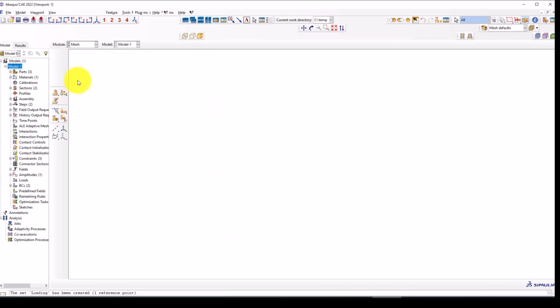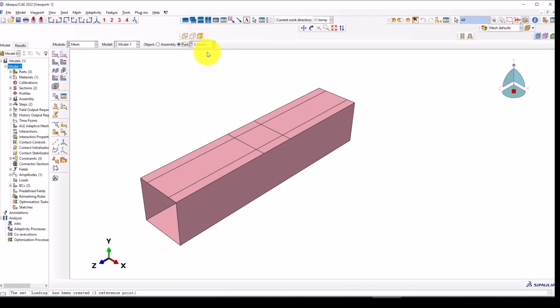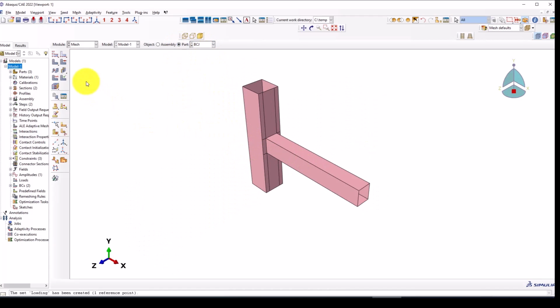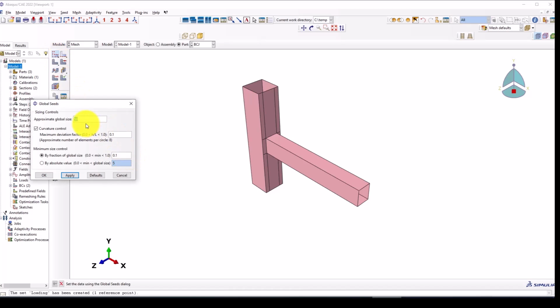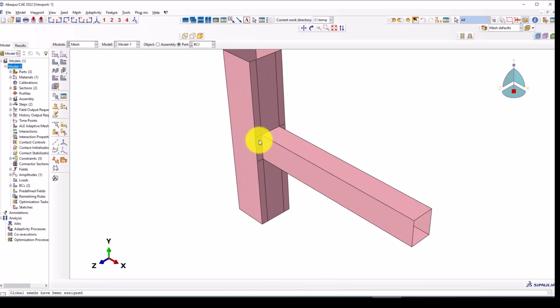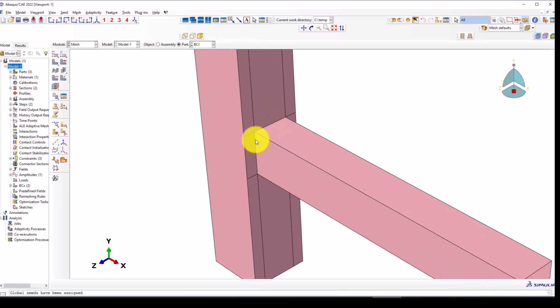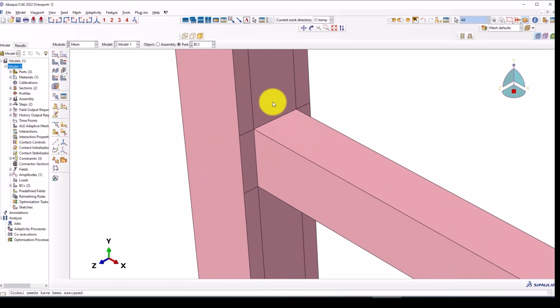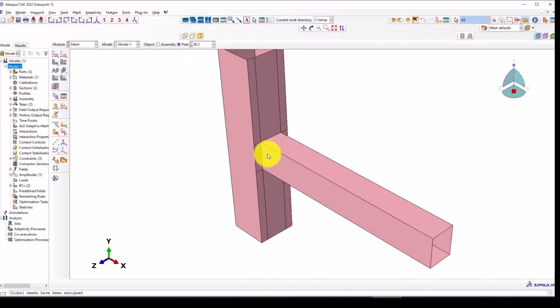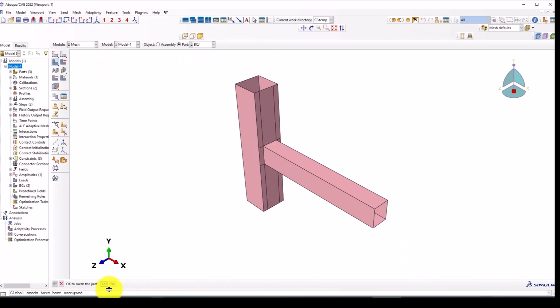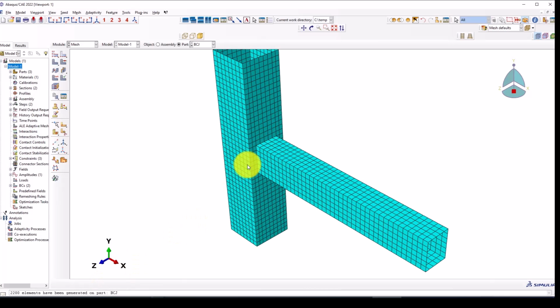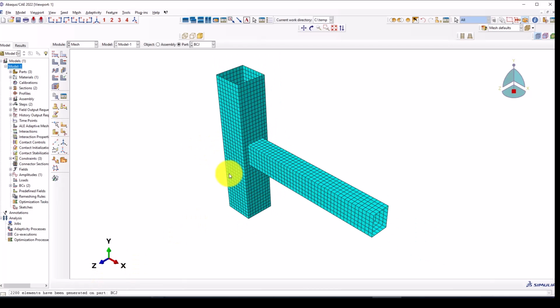Now we don't have anything else, and just we should apply the mesh. Here in the meshing, we want to create a fine mesh. Even you can select these elements using a fine mesh, and other elements should be coarse mesh. It doesn't matter because the most important area is this area, this part here. Now we can say mesh yes. So the mesh is totally uniform fine mesh.